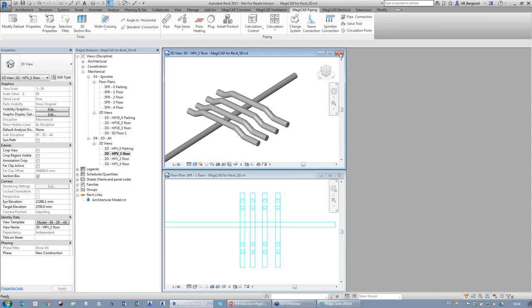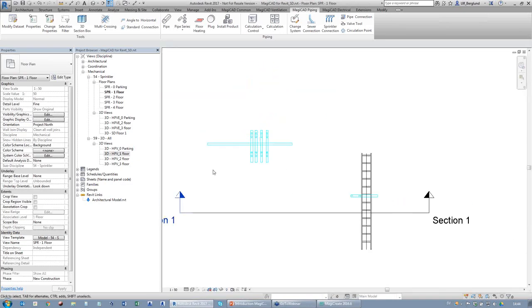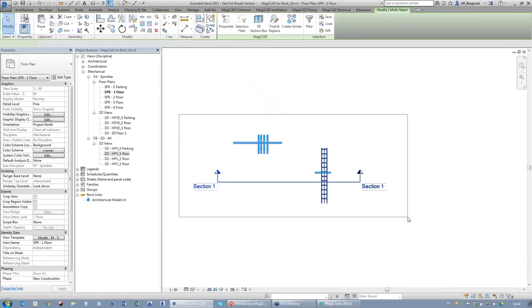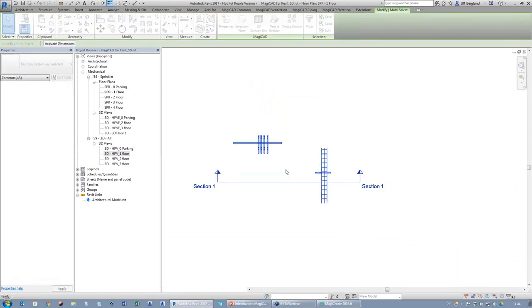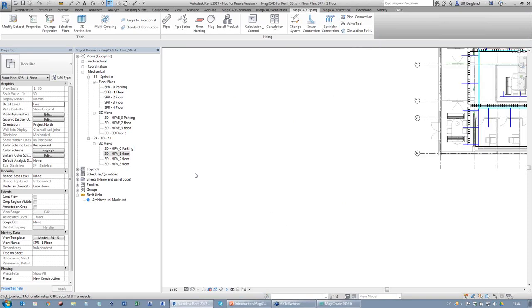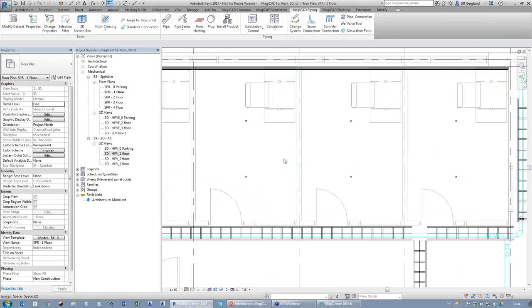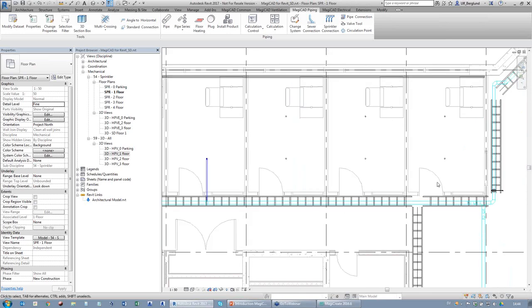So that's about the piping. Let's go and see how it looks when we want to connect some sprinklers to the pipes. So we have this connection tool that's called sprinkler connection. I have a drawing here since earlier. I have placed like 6 sprinkler heads here. We can have a lot more, but I wanted to keep it inside of the house just for this, and then I will run the calculation using this also.